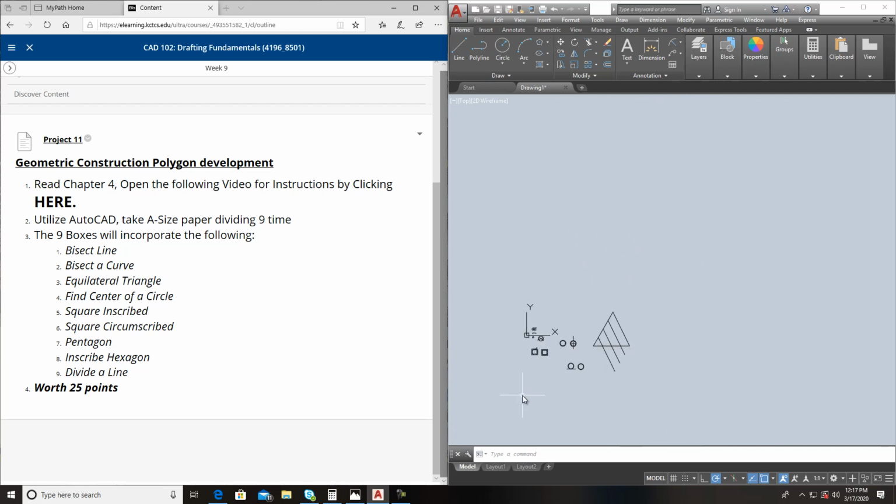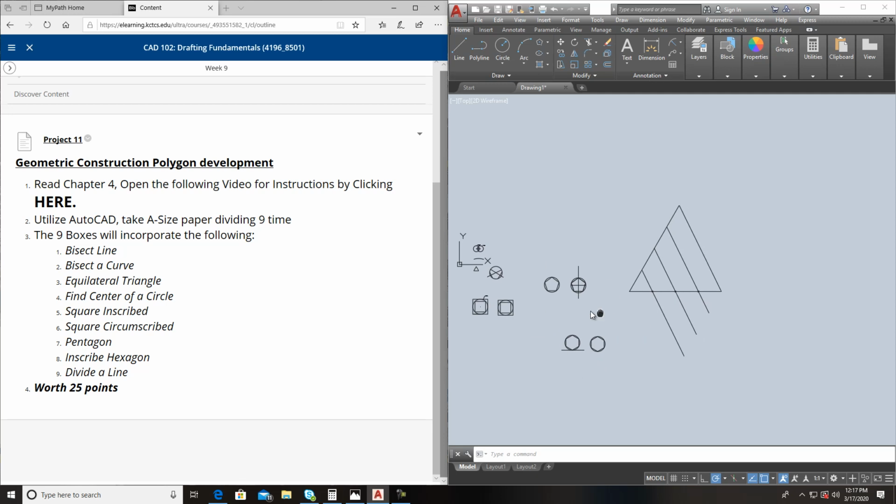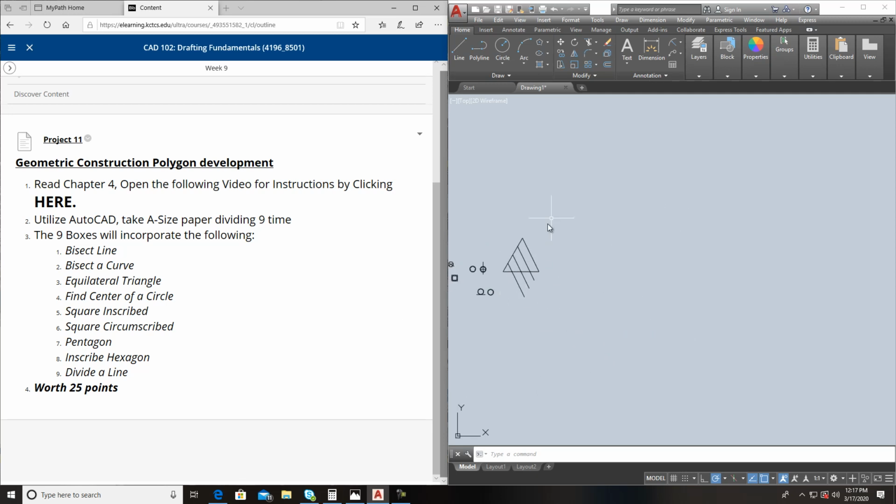So I want you guys to get, that's how you draw all these, and then I want you guys just to basically take and do a square. We'll do a rectangle, and I want to make it 11 inches in X and 9 inches in Y. And we're going to bust this thing up 9 times, okay? Because you're going to have 3 boxes here and then 4 across. So it doesn't matter. And I want to explode this because it's all one piece right now. It's a polyline. Y'all see how I exploded that?